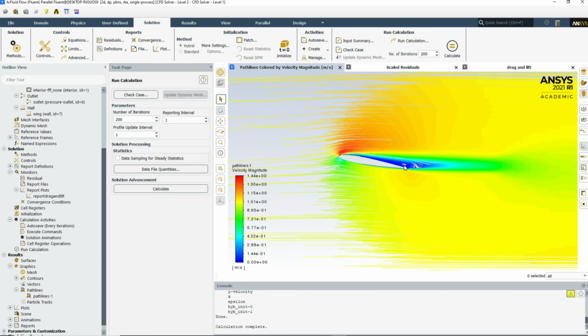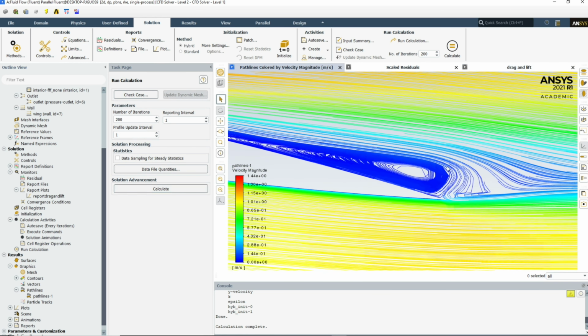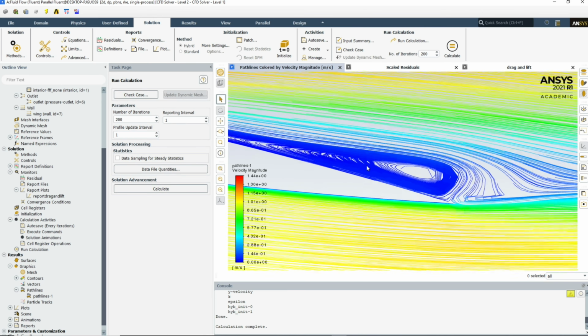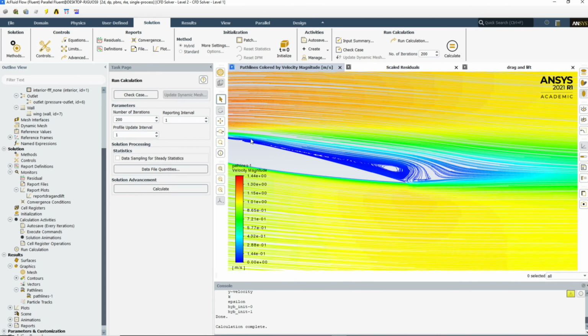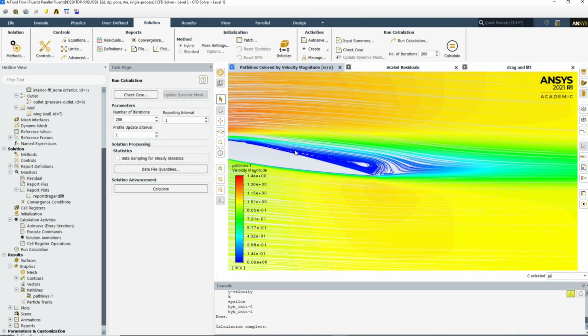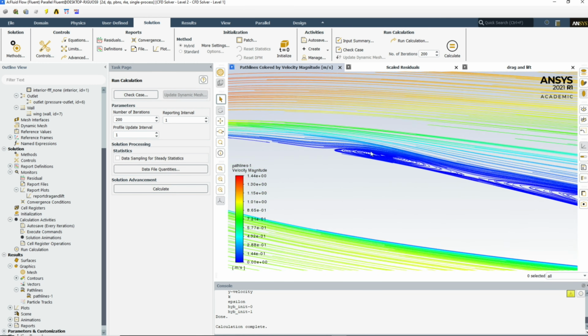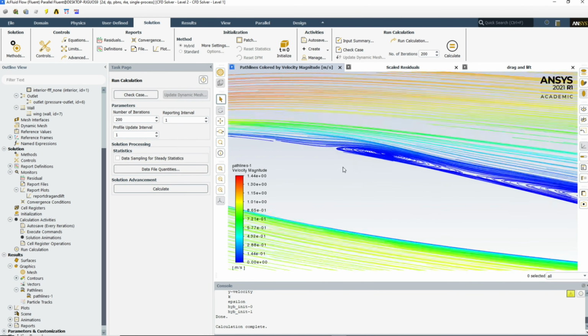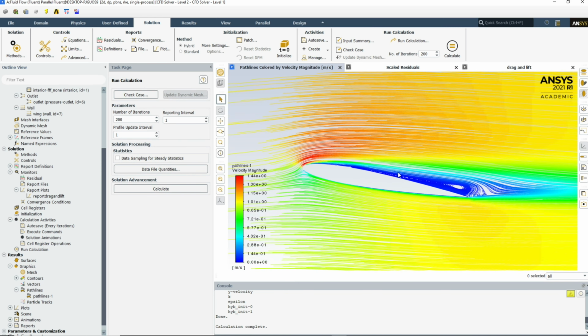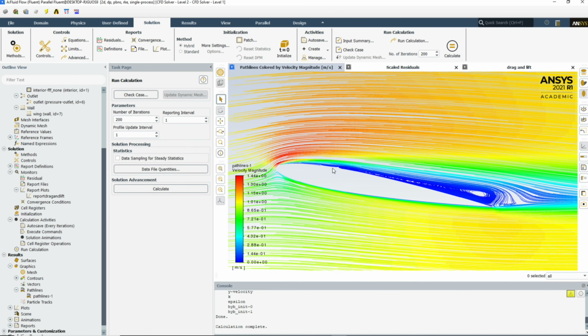And as you can see in this model, in our simulation here, we're showing that there is this separation bubble in the wake. And we've seen that in the other simulations as well. And in fact, looking deeply here, you can see that there's quite a separation bubble at this point as well. And so how that behaves will be totally dependent upon what we chose for the grid and how we modeled what's going on close to the boundary layer.